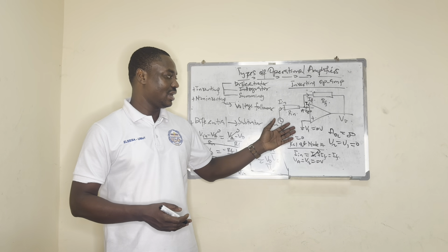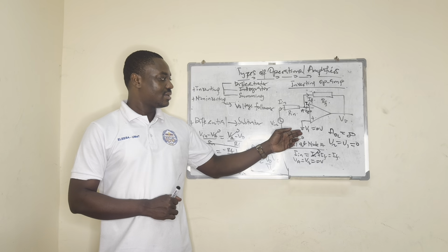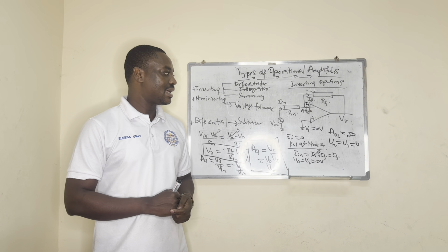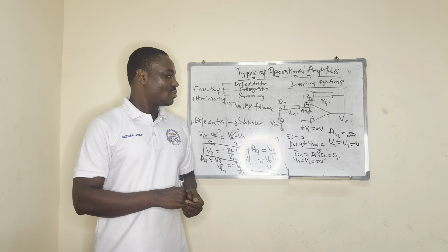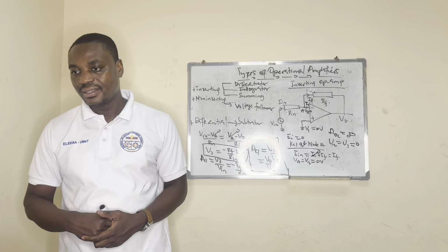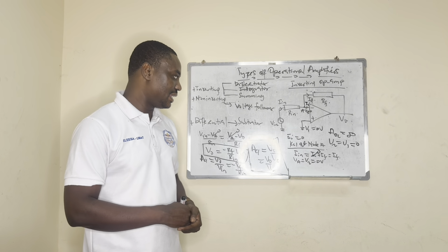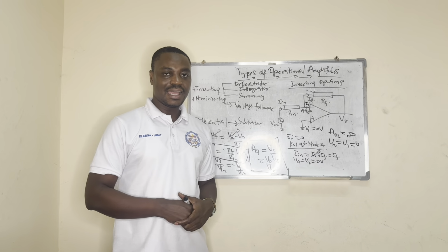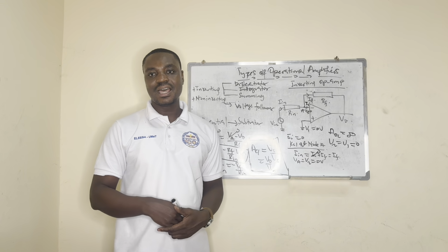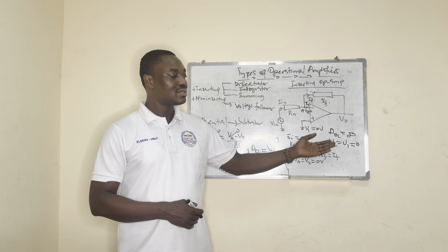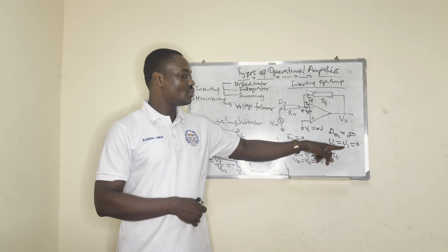So we connect it to the ground, and that means the voltage at that input terminal is going to be 0. Based on this, we know that an operational amplifier has a very large gain, meaning it has an infinite open loop voltage gain. In order to get that large open loop voltage gain, the differential input has to be 0, because V2 will be equal to V1.